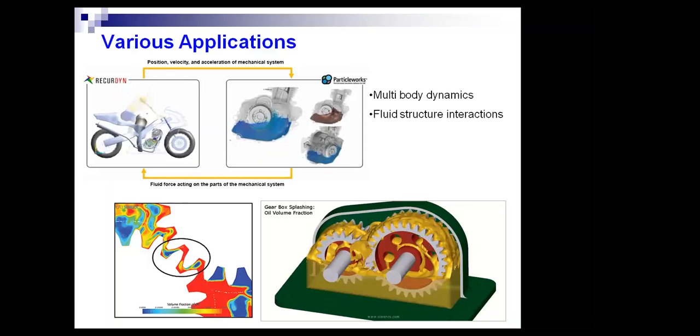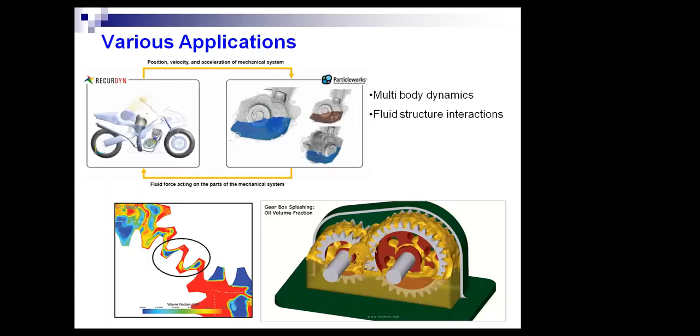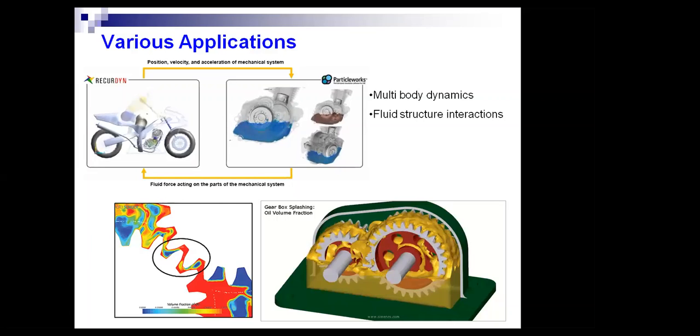And the image shown just on the left side of the gear simulations is nothing but the pressure developed between two meshing gear teeth. And this is one typical problem involved in lubrication systems, especially in gearboxes, where insufficient lubrication will lead to larger friction, thereby it will increase the wear of the component, and temperature will increase, and it will lead to worn out components.